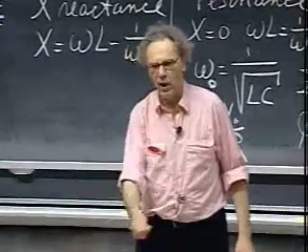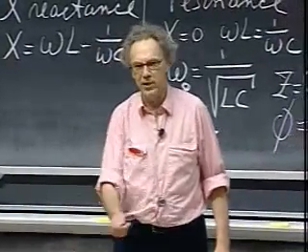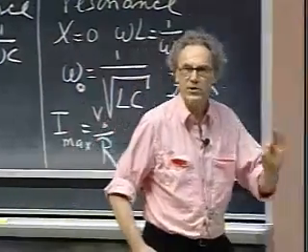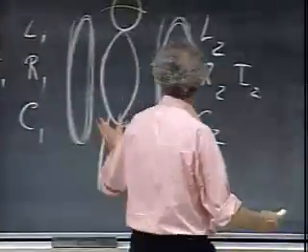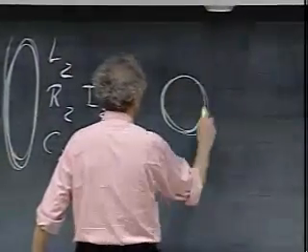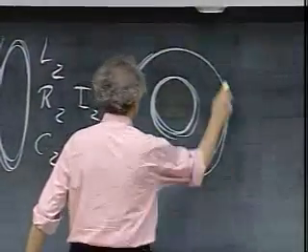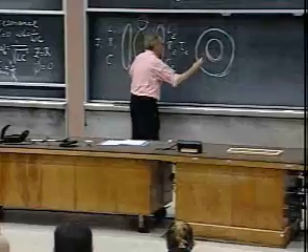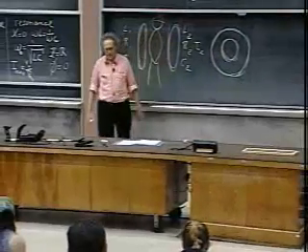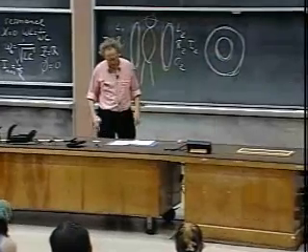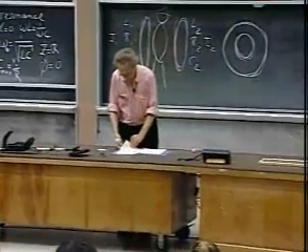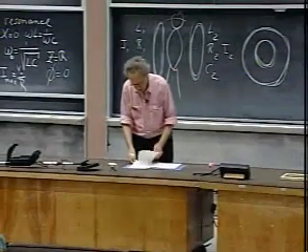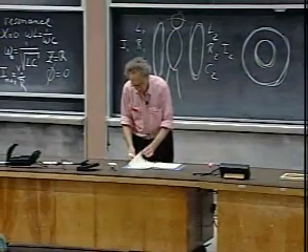When I was a kid, I went often to the beach in the Netherlands, and there were often people who were having these metal detectors. They were looking for coins. And those metal detectors, basically the same idea. Always two coils. This is this coil, and this is this coil. And when metal comes nearby, you have a system that goes off resonance. You get a difference, magnetic coupling between the two coils, and the system goes into alarm.